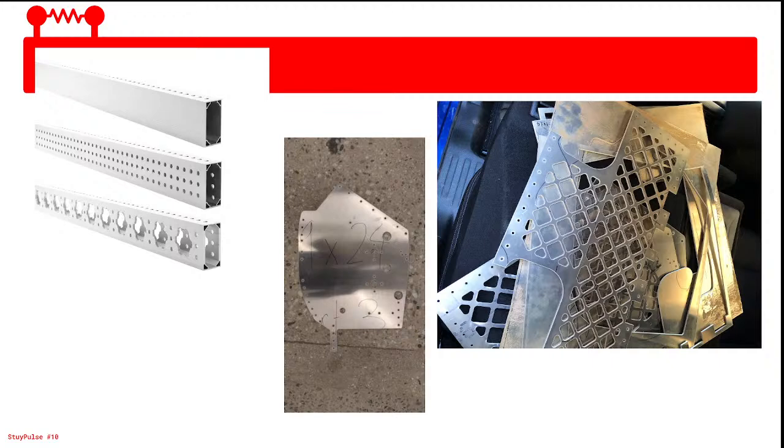This was a crossbar on our 2018 competition robot. That robot won the New York City National, went to champs, all that fun stuff. As you can see, it was bending. This crossbar held the weight of the entire robot. It's what we used to climb that year. Well, what it was attached to. Over 120 pounds of robot was going directly here, which is where the gears, the sprockets and everything were. That's where everything ran. After a while, because of all that load, it started bending and it snapped. This cost us a match. This cost us a competition.